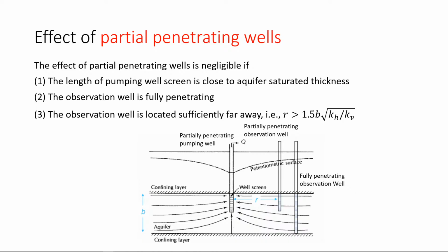Your pumping well might not be fully penetrating, as you see here. So this is a fully penetrating observation well. This is not a fully penetrating, partially penetrating observation well. And this is a partially penetrating pumping well. So you see here three examples.